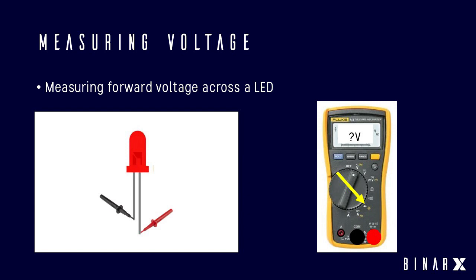Has everyone managed to get their LED to light up with the multimeter? Have a look at your LED physically, up close. One side of the LED is going to have a little flat part. Can everyone see the flat part? One side will be flatter than the other. They'll also have different length legs. Not only will it have a flat side, there'll be one leg shorter than the other. Is the longer leg negative? The long leg is positive.